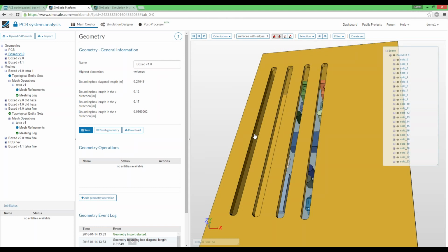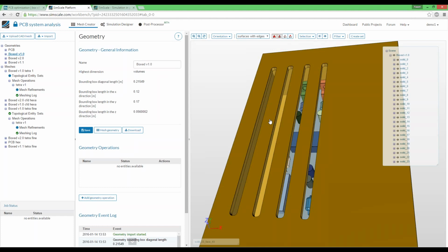After that, when we have the first surface mesh, it will be growing tetrahedrons, or basically triangles, prisms. It can also grow prisms, it can grow triangles, it can grow basically tetrahedrals. So we have this growing inside, and then there are refinements that will remove some cells, make more of them, and so on.